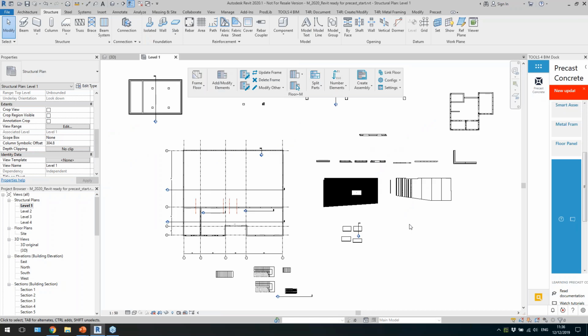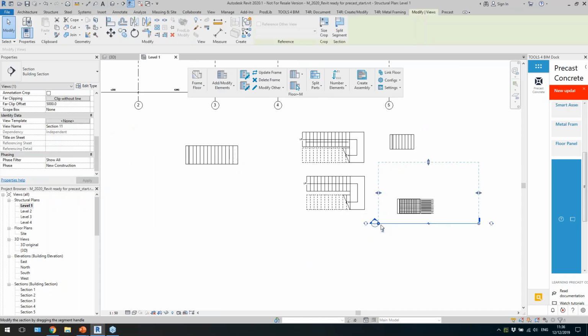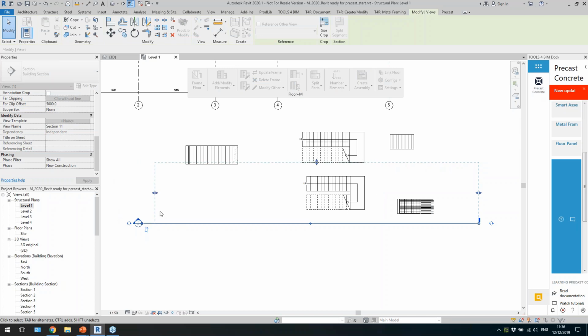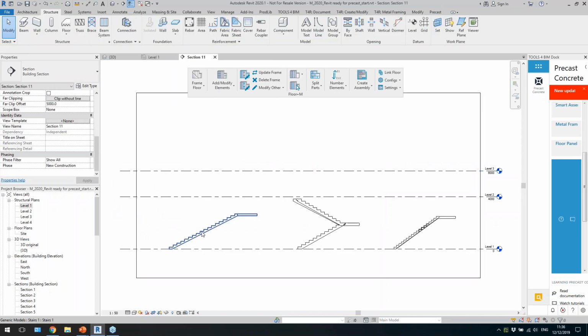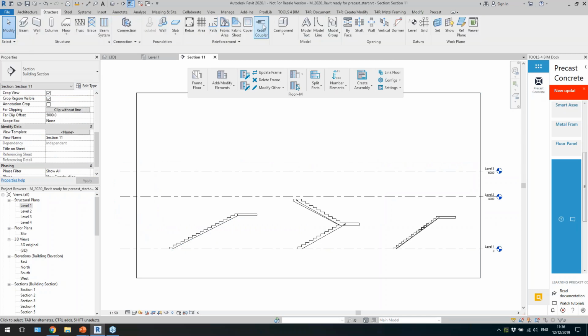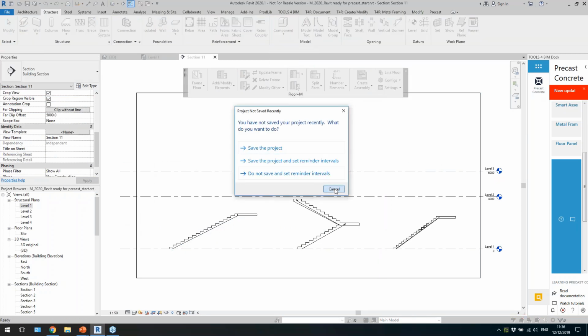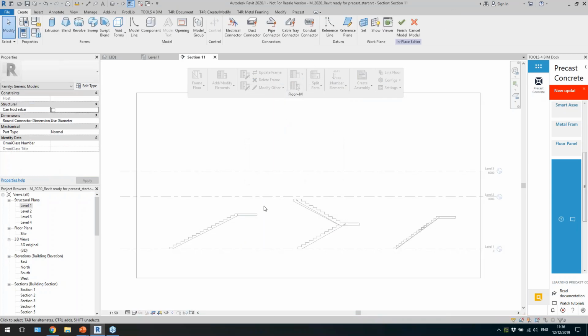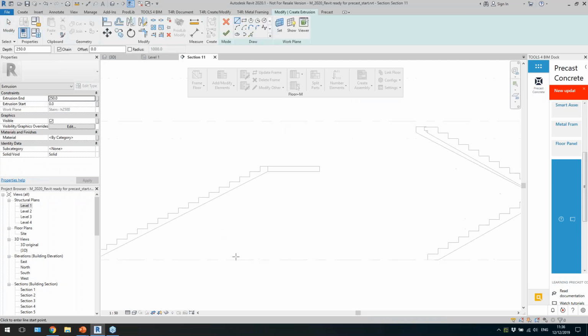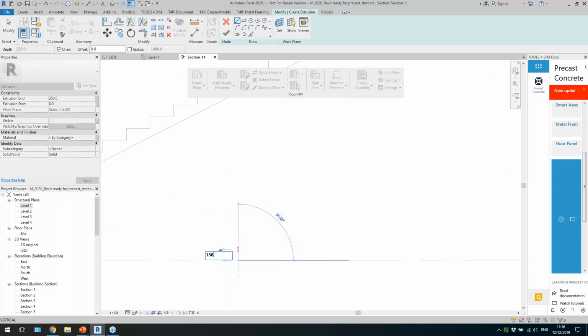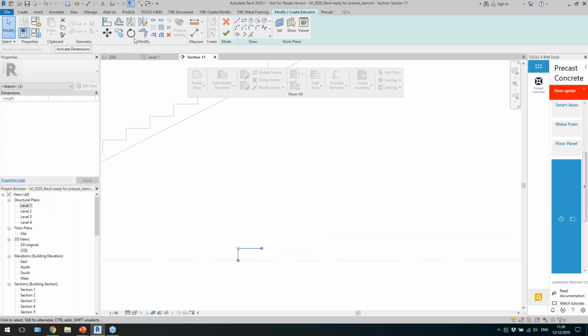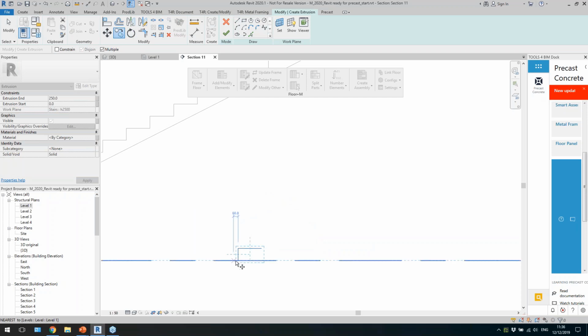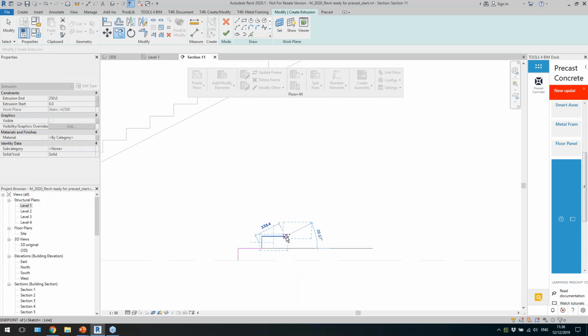The other way is you could also use the model in place possibilities in Revit. So for example, you draw the section, go to the section. All right, so we see this one, but you have this model in place option, right? So you could select just the category actually here. It depends again on whether you export this information somewhere, or how you work with it. So let me just create a couple of these stairs, right? So like that, I'll just simply draw, nothing uncommon, right?